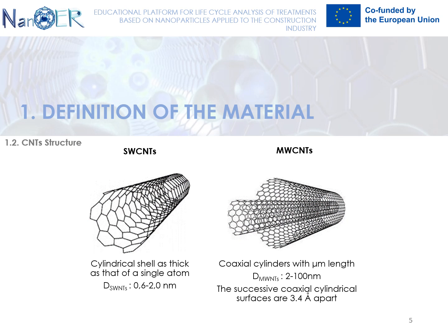Multi-walled CNTs are nanotubes consisting of coaxial cylinders with approximate diameter of 2 nanometers to 100 nanometers and a length smaller than 1 millimeter. The distance between the cylinders is 3.4 Angstrom, which is a distance 1 Angstrom bigger in comparison to the distance between graphite sheets. This difference occurs because of the cylindrical shape and the van der Waals forces which appear between the cylinders. Generally, multiple nanotubes consist of wrapped sheets forming cylinders which show lots of similarities to graphite ones.